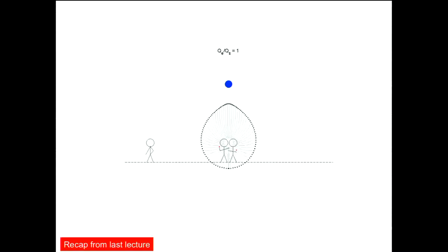In the previous lecture, I showed you this MATLAB script which I did. Well, not I, but Nick. Basically, we know our stream function, so we can find our velocities u and v. Once we know our velocity vectors, we can seed particles and watch them move. These moving particles are our streamlines, as path lines are equal to streamlines for a steady flow.